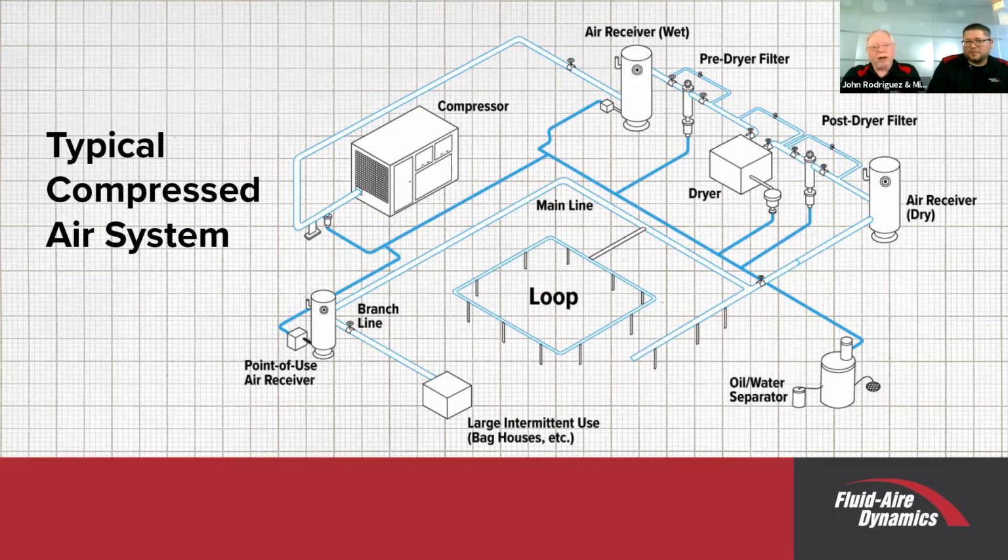And then from that, we'll go to the 0.01 micron filter that I mentioned also. Again, all these have drains. Then you go to your dry tank, which is basically your battery or your storage area. That is sized, and we can get into that in a different subject later on, but we need a lot of calculations to come up with the right size tank for you. We can handle that for you if you want to give us a ring.